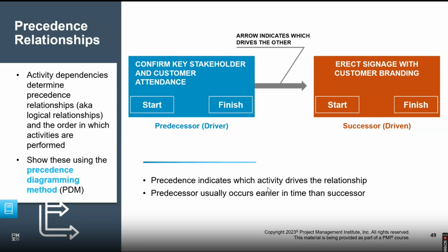When you put them in the right sequence, we also have to understand, because we'll say how much brickwork will take, how much plastering will take, how much painting will take. We're just talking about the whole activities. We're not talking about the dependencies between those activities that could result in a lag, because one activity when it's done might need some buffer, some gap before I can resume with the second one. So that will create a lag time.